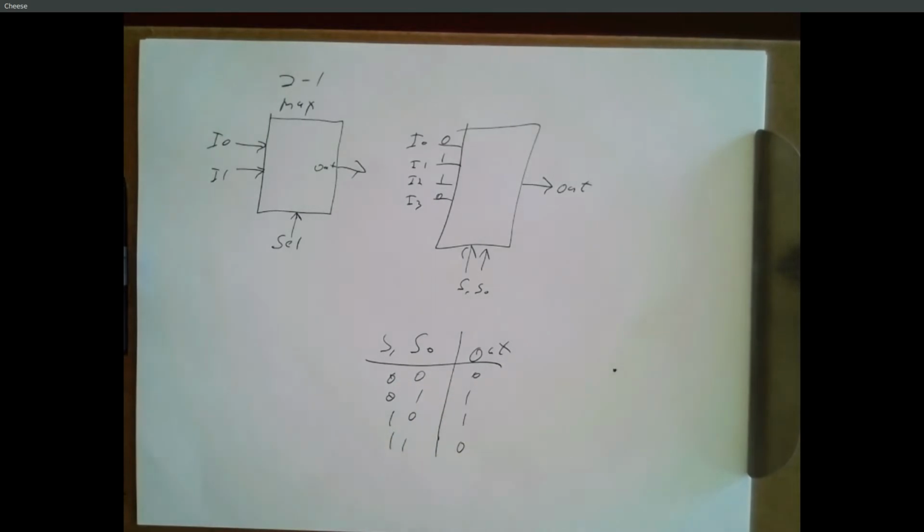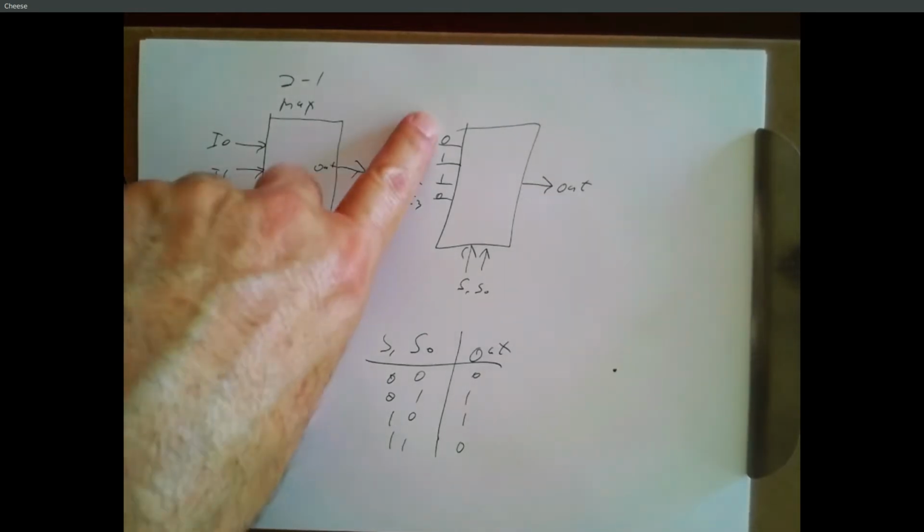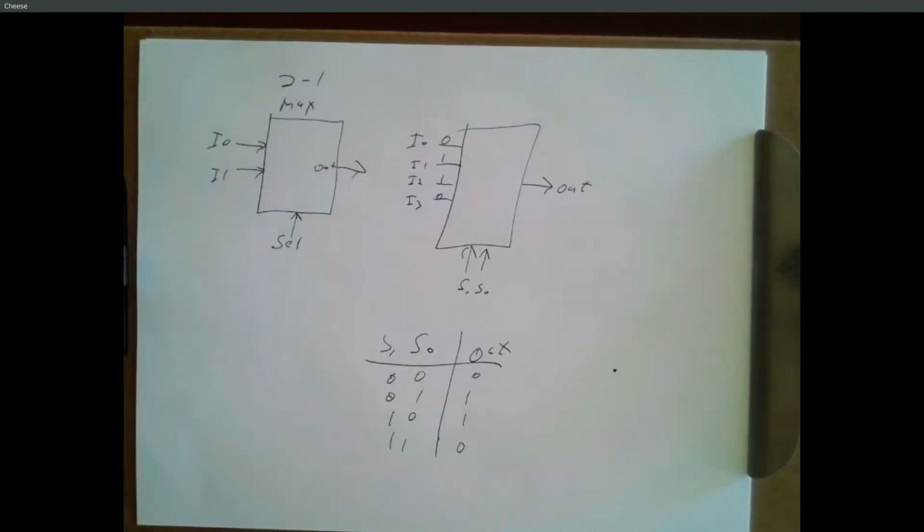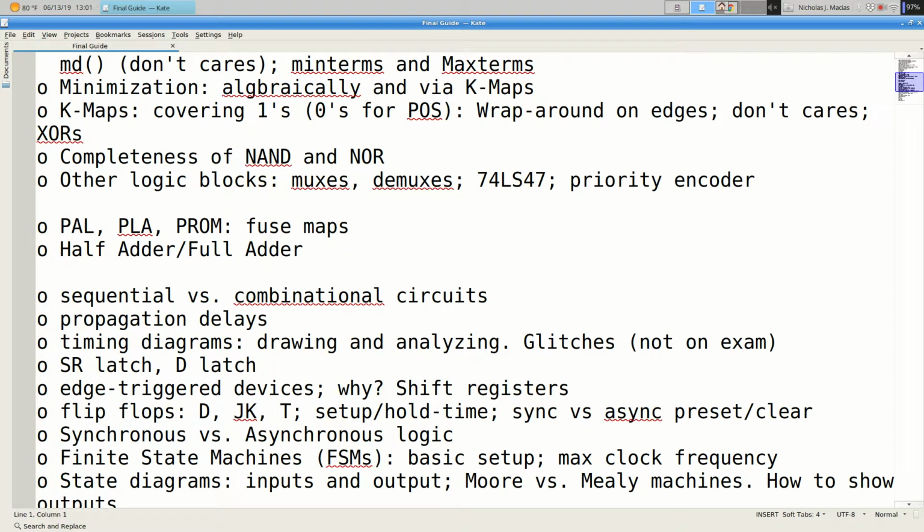So we can implement any truth table that we want using multiplexers. And this is what FPGAs do internally. They have multiplexers and they set up the inputs according to whatever you configured the device to do, and it acts like a truth table basically. So these are called LUTs, sometimes lookup tables. And it'll say how many LUTs you have in your device and so on. Those are basically your random logic elements. So multiplexers work like that.